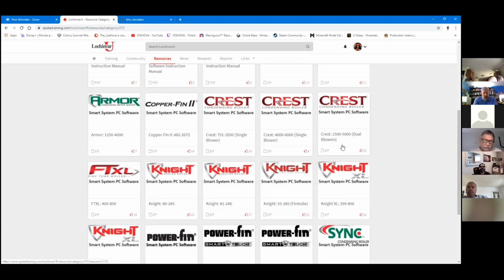So let's say, for example, you have a unit that's giving you trouble, it always fails at 3 a.m. The old days of getting a cot and wasting 2 days, that's over. You don't have to do that. Take a cheap little laptop, hook it up to the boiler through the USB drive, put this software on the PC, and let it do a log file overnight. Remember, there's a video on how to do a log file. There's a video on how to download this software. So we show you how to do that.